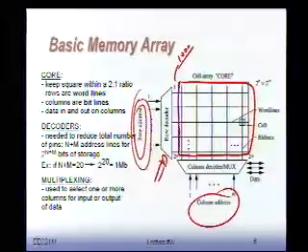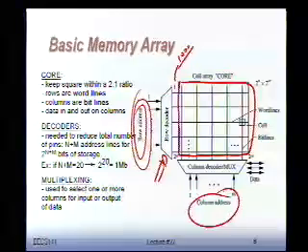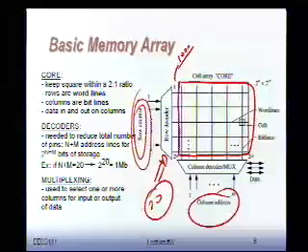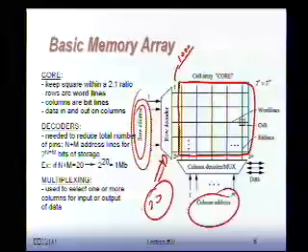And the same thing is true with the column decoder. Out of 1000 columns, I select one column. So the total address is now only 20 bits. That's a lot more manageable. Now decoders are basically giant arrays of NOR and NAND gates. Bottom line, large, very complex NOR and NAND gates. You can choose how you implement it, but these are big fan-in gates. Like here you have 10 inputs, 1 output, and you have 1000 of those gates. That's really what a decoder is.